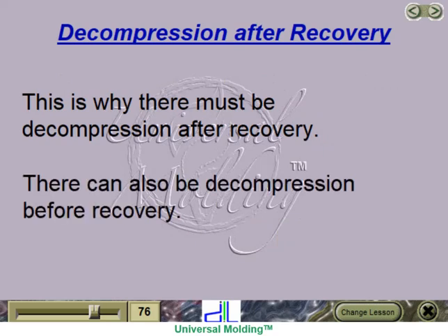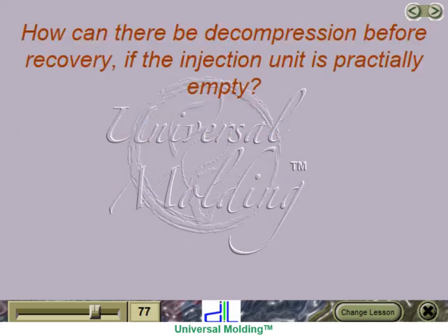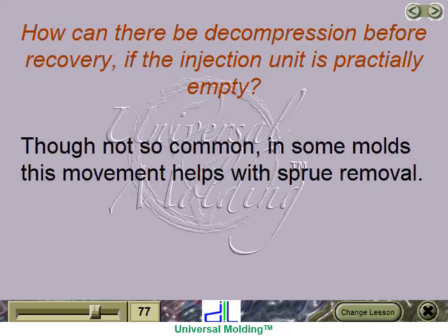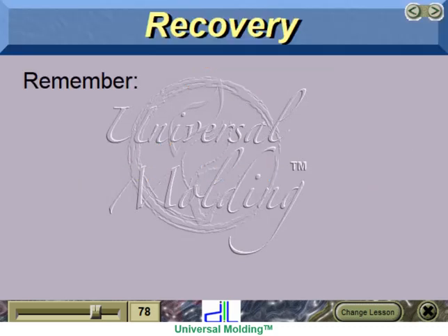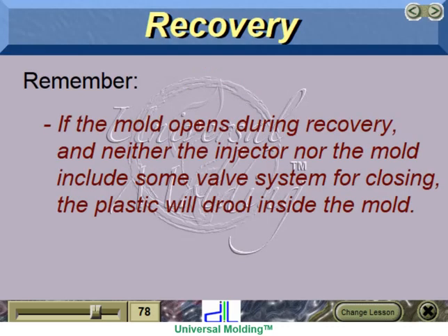There can also be decompression before recovery. How can there be decompression before recovery if the injection unit is practically empty? Though not so common, in some molds this movement helps with sprue removal. Remember, if the mold opens during recovery and neither the injector nor the mold includes some valve system for closing, the plastic will drool inside the mold.